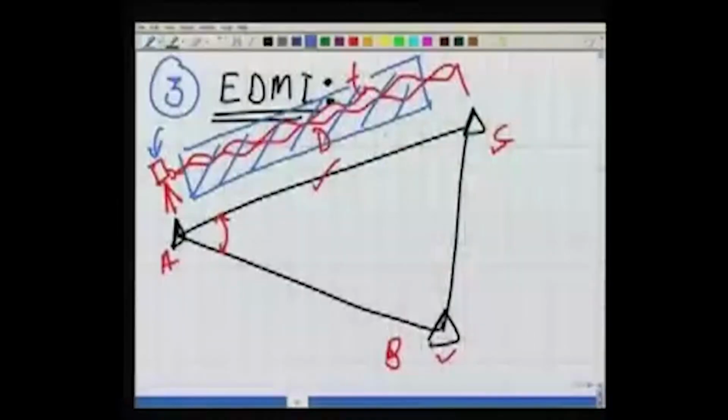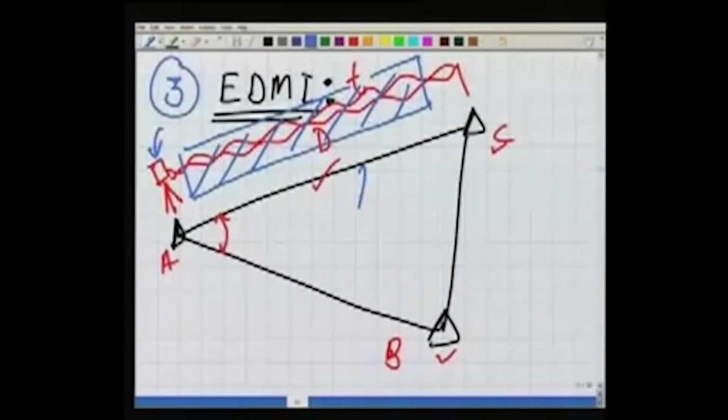So we should not use the C for vacuum. No, we cannot. We have to use it for the actual atmospheric conditions. Now, measuring those actual atmospheric conditions across this length of 2 km is not a possible task. We cannot do it. So because of that reason, there will be some error again in these length measurements.